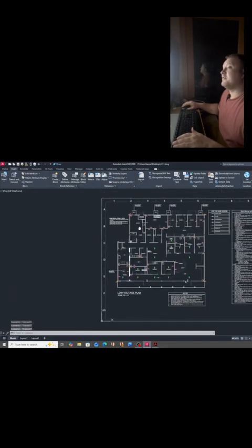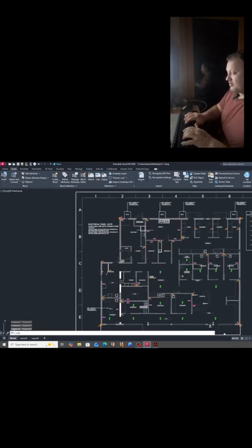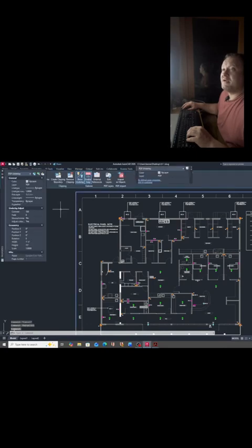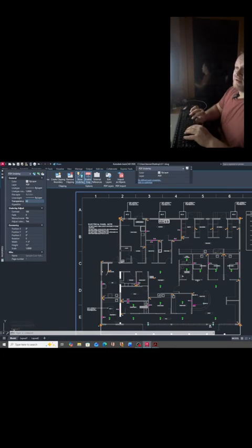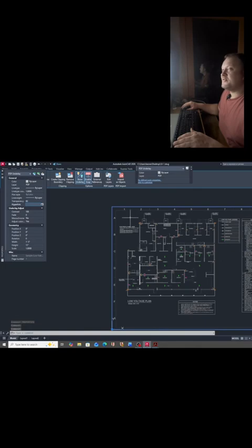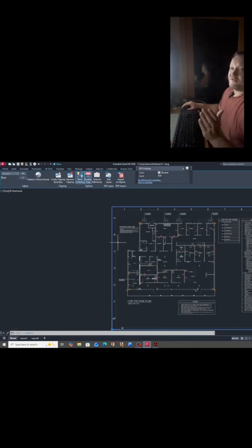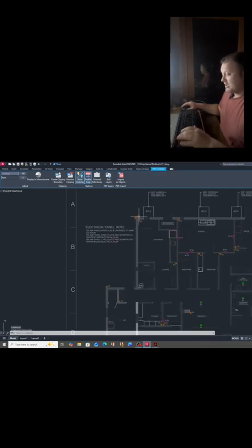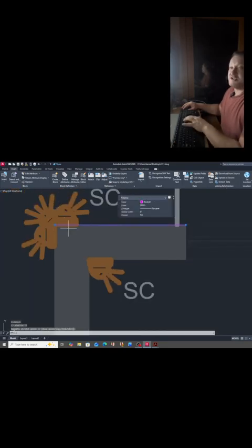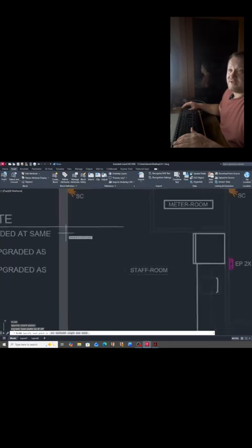Oh, one other trick I do, you guys, sorry. If you type in properties, select the PDF, and if you set the transparency, I'm going to set it to 60. So what this will do is it kind of makes this so that it's see-through, and you can go anywhere from 0 to 100. 0 is, it's not see-through at all. 60 is pretty transparent. And now as I create my lines, we'll be able to see where they are much easier than if things weren't transparent.